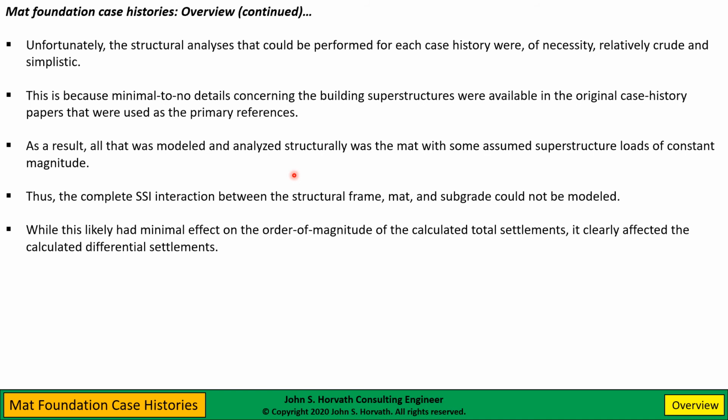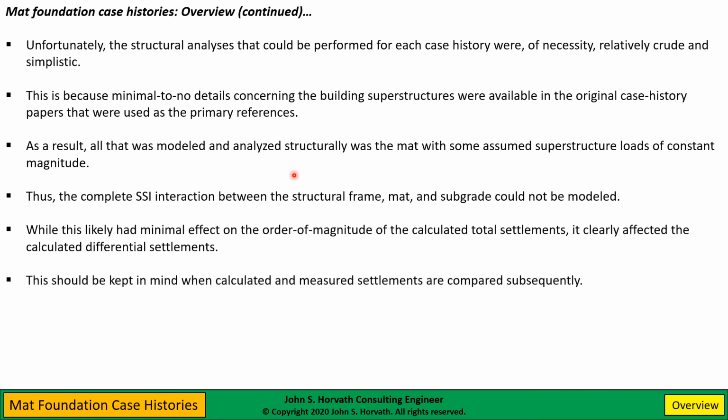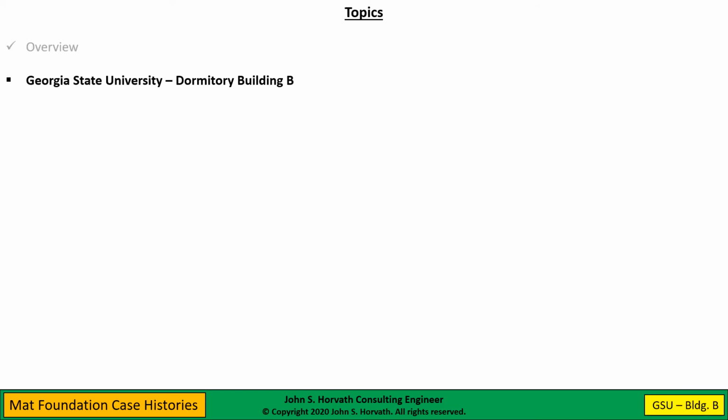But I think the differential settlements were inaccurate to varying amounts because of the inability to truly model the real structural mat and subgrade interaction that was going on. So you just need to keep some of these limitations in mind when you look at some of the comparisons that are presented subsequently.